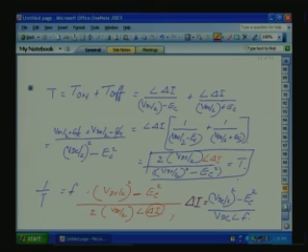So, there should be a compromise. From this one, for a fixed DC link and a fixed switching frequency, delta I can be found out. With a fixed tolerance band, the switching frequency F depends on the output voltage required. Now, let us take EC. EC is varying.